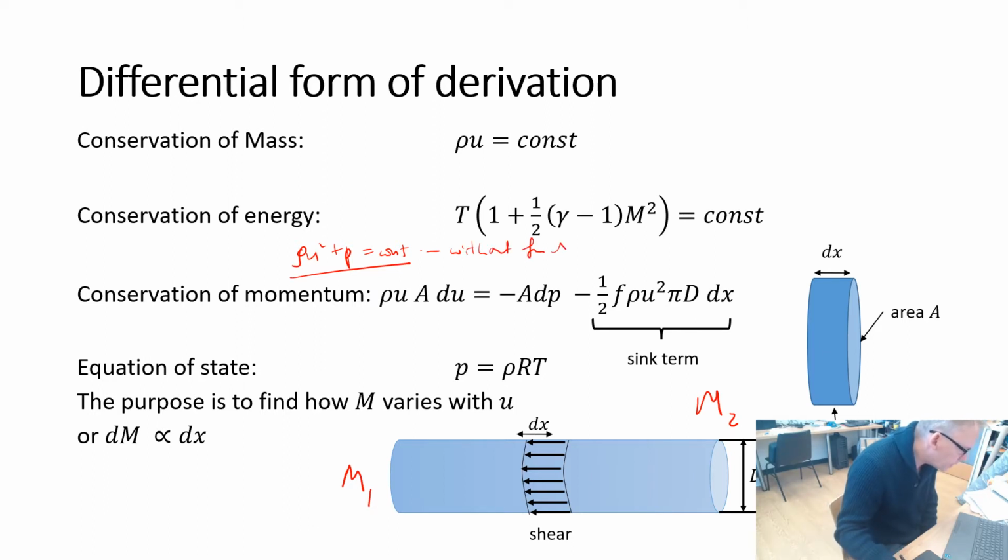And so if we're looking at how friction changes things, then we're really trying to look at how parts of this decrease due to the effect of friction on the walls. So d/dx will not be zero when there's friction, whereas it is zero without friction.